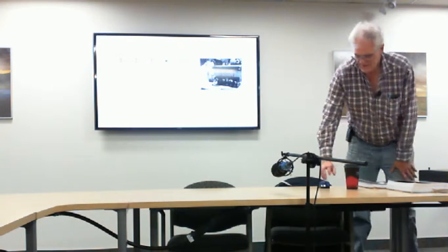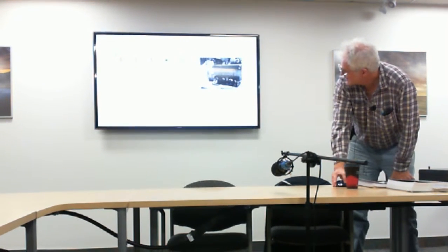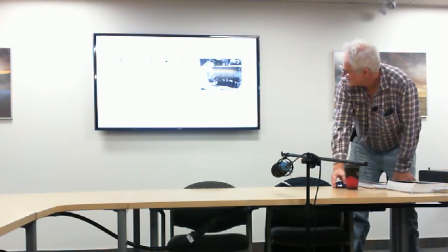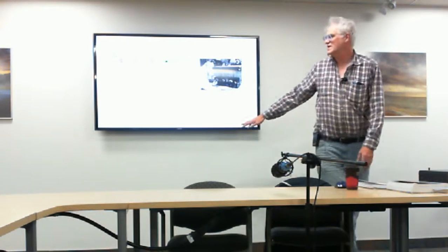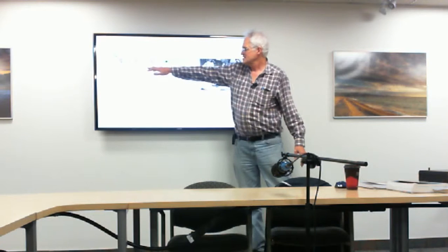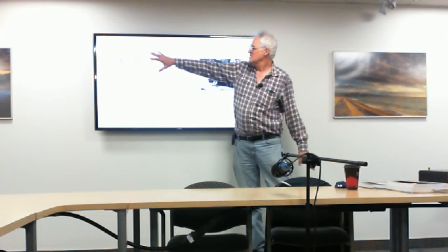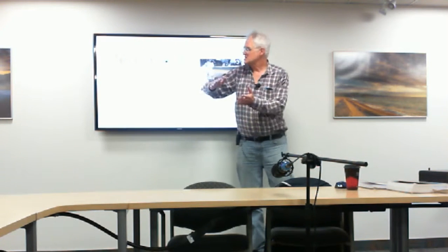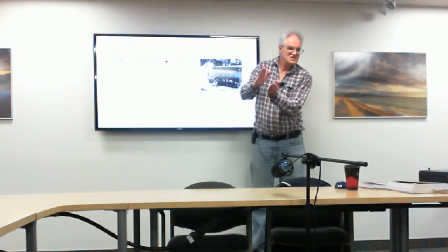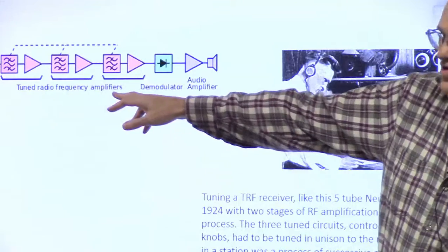But we progressed. And the problem with something like that is this section had to be broadband enough so that we could receive all of the frequencies that we would ever want to listen to. So to make a receiver that broadband, it's not very selective, right? It's harder to tune to a specific single frequency that you want.